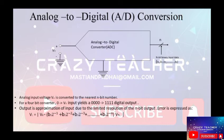So the output is again an approximation of the input data, due to the limited resolution of this n-bit output. As for the error, this is actually the Vx that we want to represent, but what we actually get is this one. If all these bits are 1, then you will be getting a value which is very close to VFS, but this value is VFS. So VFS minus that approximation gives the amount of error that you have in the process. This way we can have the analog to digital conversion.